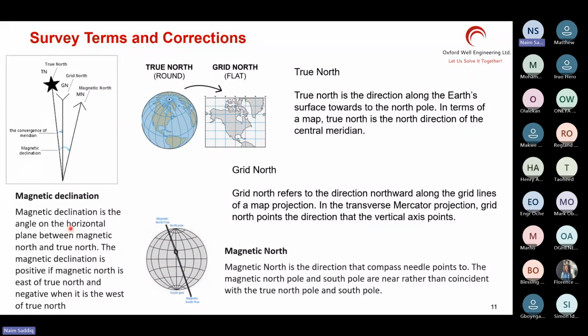If I give you the values for magnetic declination and grid north corrections, then you can apply them. These are things you can probably learn in a proper course, but be aware of these corrections. If you do not correct the surveys properly, each and every survey you take will be incorrect. It's a systematic error you impose on the location of your well. Your well will be in a completely different place if you get this wrong. It is critical to respect the survey correction.